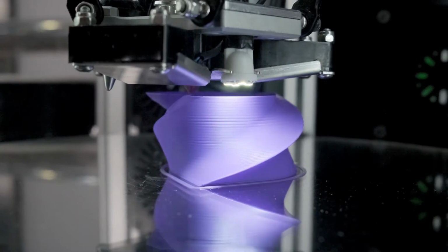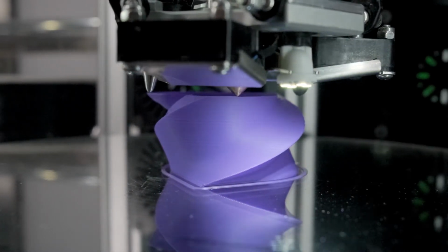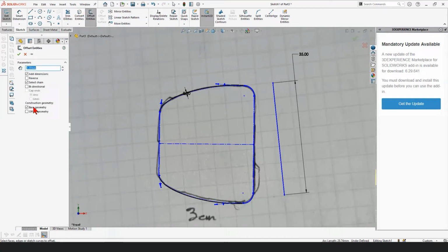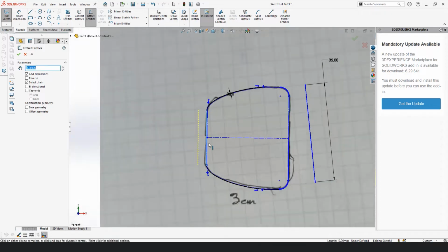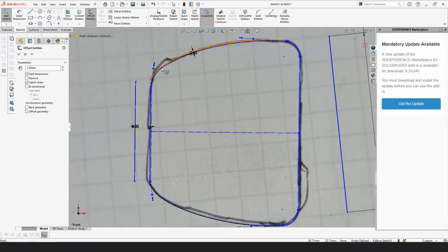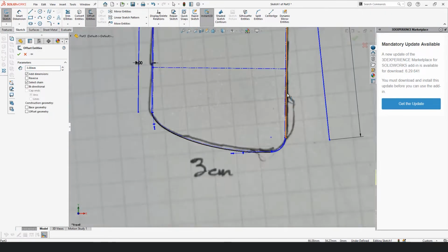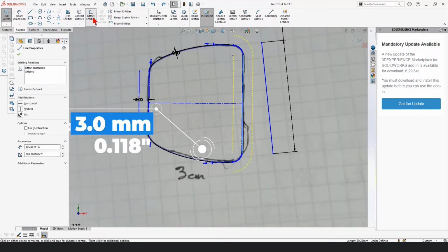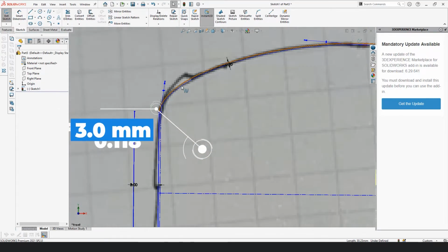It's dependent on my manufacturing process again. Since I'm planning to 3D print this component, I think a 2 or 3 millimeter wall thickness would do fine. Since it's going to be from PA12, it's strong enough, it's not going to break. So I'm going to go with 3 and offset this value 3. That defines the outer edges of my pocket. Right, now we have one closed sketch.